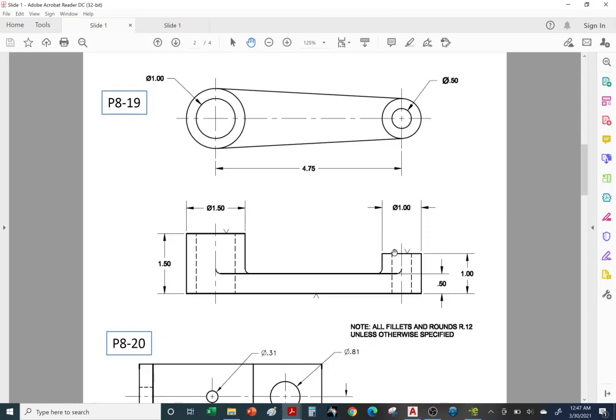Right? Same thing with this one. It'll have a rough surface, and at the bottom, a rough surface. So you come in and just machine off a nice planar surface, a nice smooth surface, so it can easily mate up with its other parts, whether it's a vehicle or another assembly other than a vehicle.